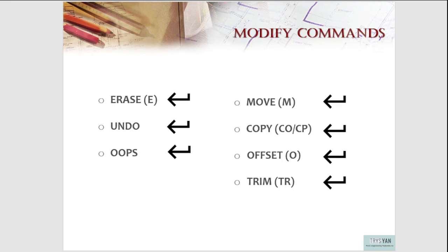Then I will make a line like this. Or I will just offset it, no? So from the previous command that we made earlier, so offset, enter, and then the offset distance that is given to us is the previous offset distance. So I will just use this value. So I will just press enter or space bar. Ayan.